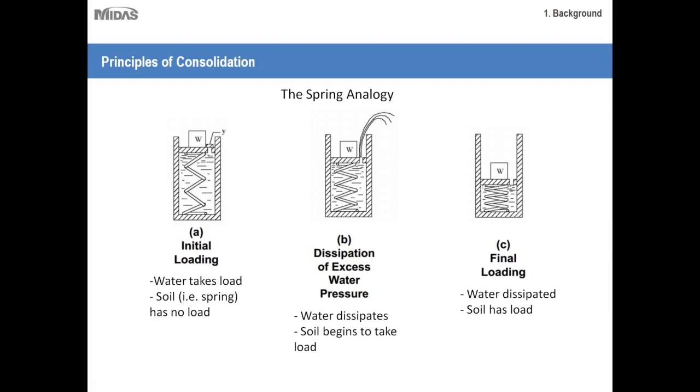So actually, when most clay soils that are saturated, when you first place your structure and your load upon the soil, it actually won't settle right away. There'll be some quick, immediate settlement, but the really long-term consolidation is actually something that can take, like I said, an extended period of time. And then in the second stage here, this is when consolidation occurs.